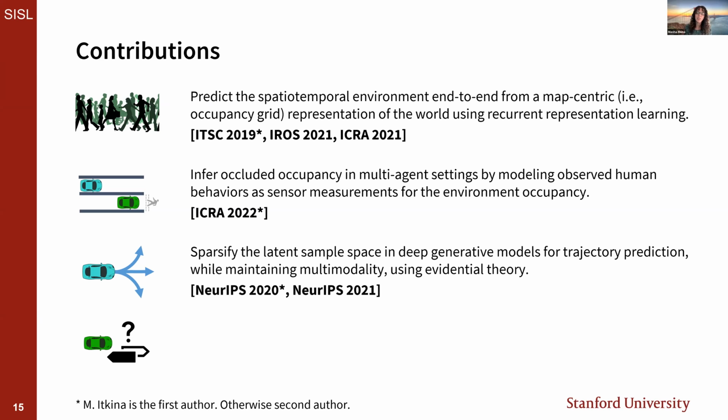In order to safely integrate human behavior modeling into the robot autonomy stack, the perception system must also account for uncertainty. Thus, we need to consider how we can efficiently model the output uncertainty or the multimodality in the output in our case. For example, in a trajectory prediction task, given a straight path trajectory, an agent may continue straight or make a turn in the future. Capturing this uncertainty in a tractable manner was the focus of our work here. We proposed a means to sparsify a discrete latent distribution in a deep generative model for trajectory prediction without compromising its performance.